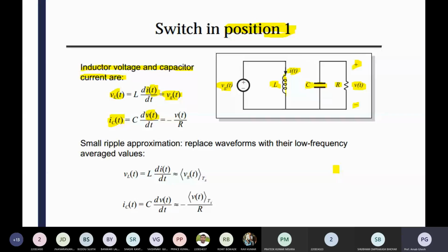So on the x-axis you are considering one state variable, and on the y-axis you are considering another state variable. So x comma y means, for every instant, the inductor current and the capacitor voltage. You can plot the value at every instant. Time is not on either axis, but you know that the points are taken after a regular interval of time.